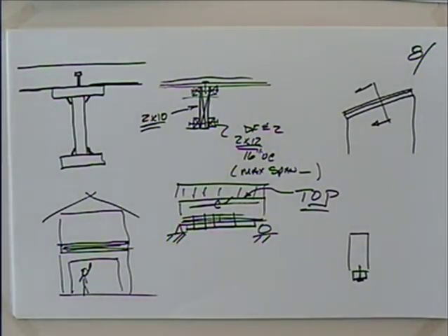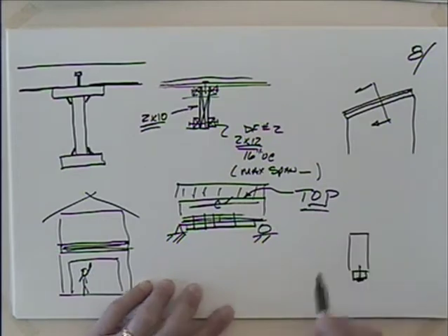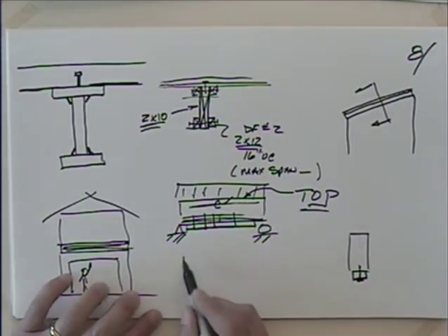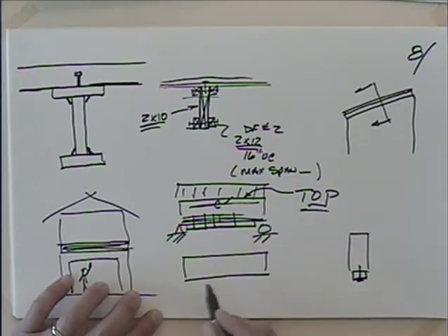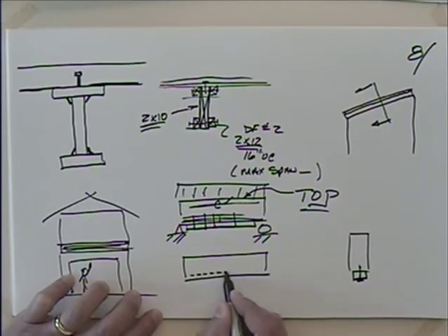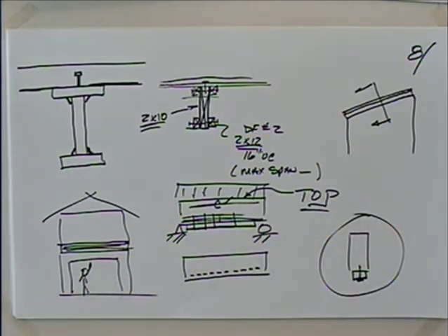Now the civil engineers are going to go on to do a lot of this, and not because they're fixing people's mistakes, but from the get-go. What if we look at a concrete beam? If we say that this example was a concrete beam, again with compression, does concrete handle compression well? Yeah, but how about tension? Not so good. So what do? We put reinforcing bar in there, don't we? And you will actually analyze that very similarly to what I had to do to retrofit that steel beam. I mean that wood beam.